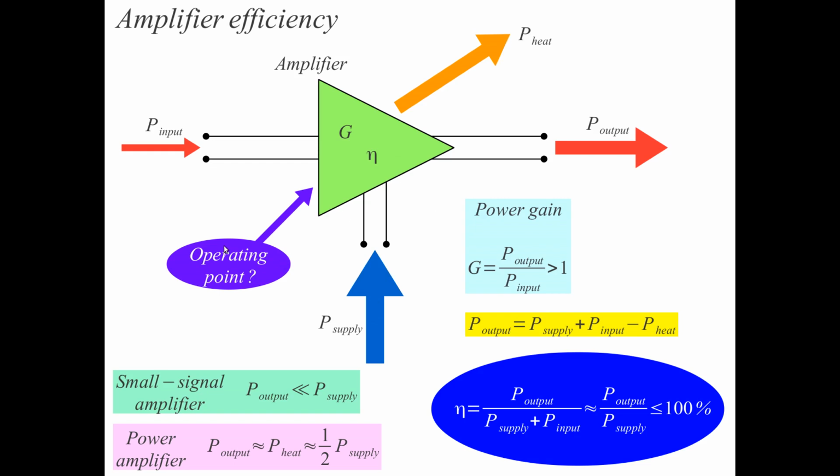Talking about efficiency, we have to think about the operating point of the active device used in our amplifier. There are some active devices where we cannot actually adjust the operating point, like a laser amplifier or traveling wave tube for microwaves. But for many amplifiers using simple gridded vacuum tubes or many kinds of transistors, semiconductor devices, we can select the operating point maybe to improve the efficiency of this amplifier. For today, for the first hour, we are only going to talk about Class A amplifiers to keep things as simple as possible. So the same kind of amplifiers we are using for amplifying small signals.